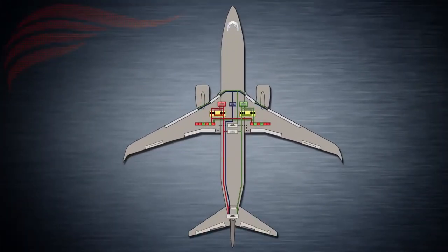The leading edge flaps and slats are sequenced to extend and retract as a function of the trailing edge flaps position. This occurs in two stages. When the flap lever is moved from its up detent into the 1, 2, or 5 position, the trailing edge flaps move to their respective position. Along with this, the leading edge flaps extend completely and the leading edge slats extend only halfway.